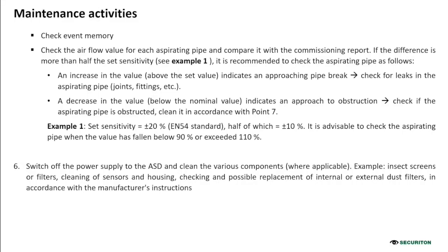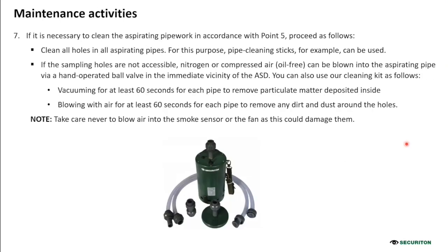Please go ahead. Okay, then we see if it is necessary to clean the aspirating pipework in accordance with the 0.5. Whenever we see that the airflow is decreasing, depending on the ambient conditions, we can clean all holes in the aspirating pipes.